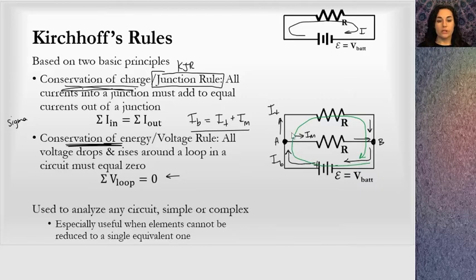What I see going on in that loop, and how we can rationalize that it should equal 0, is that we have a battery voltage here, 9 volts. Over on the other side, we're at the negative plate of the battery, the only battery in the circuit, so we know that should be 0 volts. Conventional current will flow from high to low potential. So when I go around this loop, I think about all the voltage drops and voltage rises along that loop.